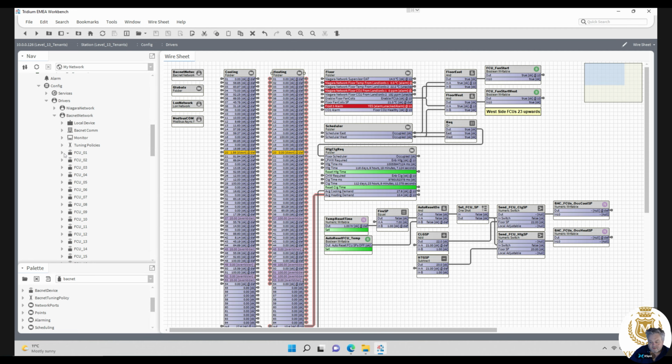So that's all the cooling valves now done, and heating valves. What I'm concerned about is this down here. See this cooling valve 50 on line 51, which is fan coil 53, is controlling itself to 100% cooling, yet someone has overridden the heating valve to 100%. So what I'm going to do now is go and take these overrides off. So we'll start with fan coil 53.